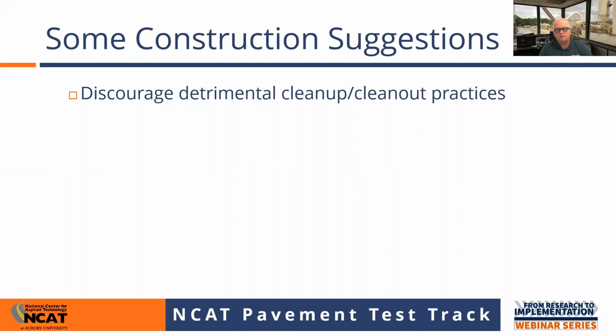And one of the things that I think we can think about doing is incentivizing using non-detrimental cleanup and clean out practices. And really what I mean by that is think about maybe working on your QPL, your qualified products list, and come up with some products that contractors can use at the end of the day or at the end of the paving run, if it's a night paving job, to clean all the equipment out, to clean everything up and to get reset and ready for the next day, and use some products that don't have any kind of a cutback or stripping effect on the mix. And there are some good release agent products out there.